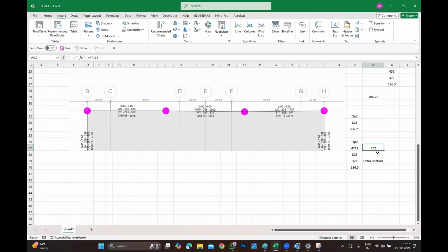It's an FEM method, finite element analysis. The whole plate is going to withstand. When you're talking about a flat slab, the moment is different from one location to another. The flat slab is a different concept than the frame element. In a frame element, you do have beams, so you can say directly it's a one-way slab or two-way slab. When you're talking about a flat slab, it is not the same concept as a frame, because the moment and the behavior of the slab are different. Getting the point, right?